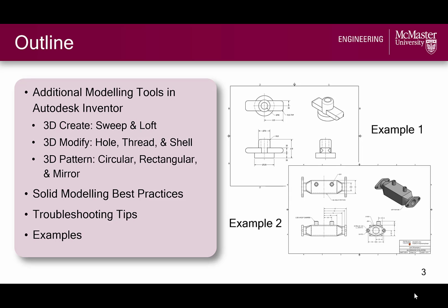In this video, we will introduce some more tools at our disposal, namely the 3D tools Sweep and Loft, the 3D Modify tools Thread, Shell, and Hole, which we already introduced in the last video, and some handy 3D pattern tools. As with the Lab 1 video, 2 examples will be walked through in accompanying videos, where we will also talk about some solid modeling best practices.